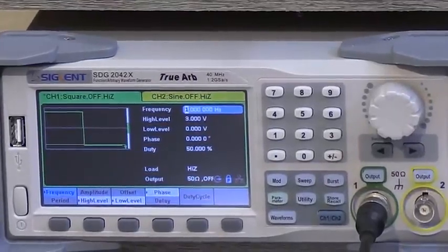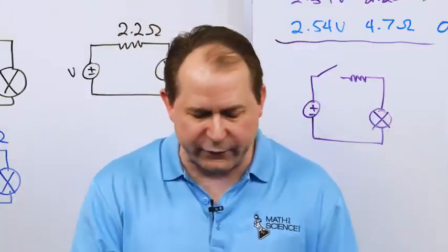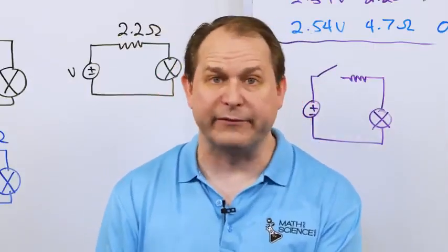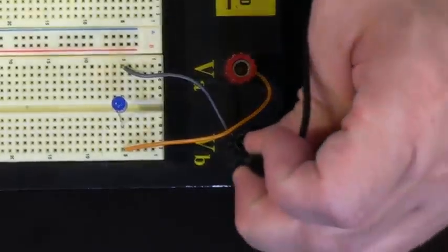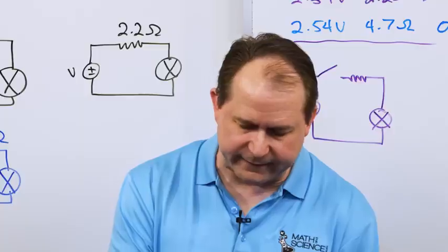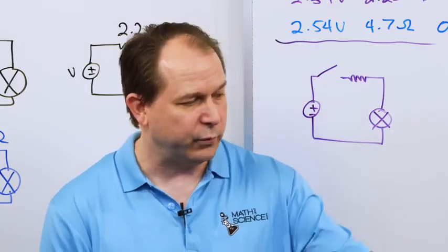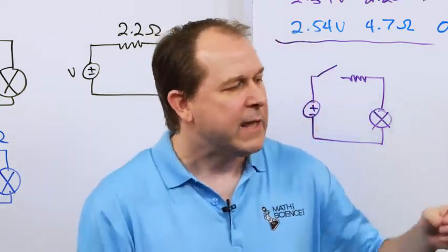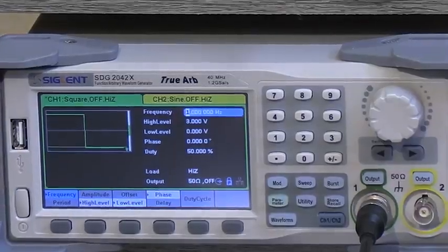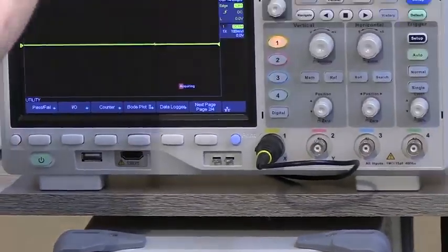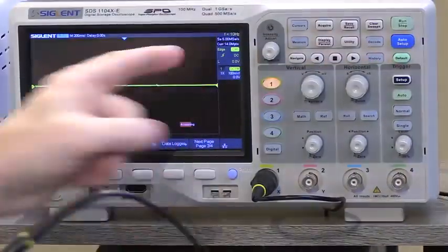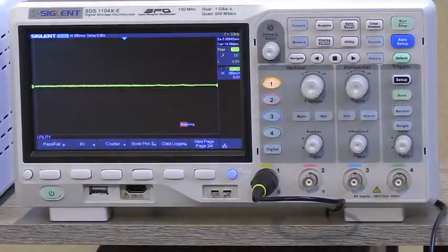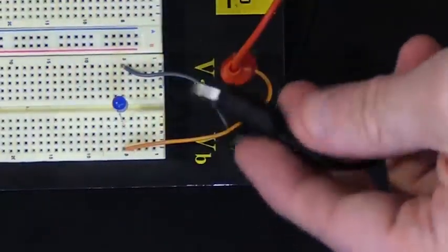It allows me to drive a sine wave or a square wave or whatever into anything I want. And so what I'm going to do is instead of driving it with that power supply, which is a fixed voltage, drive it with a square wave, basically on, off. It turns it on and off, okay? And because I'd like to look at it at the same time that we are measuring it, I have this top piece of equipment called an oscilloscope, and that allows us to actually watch what's happening in real time.